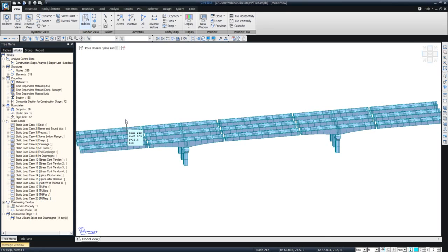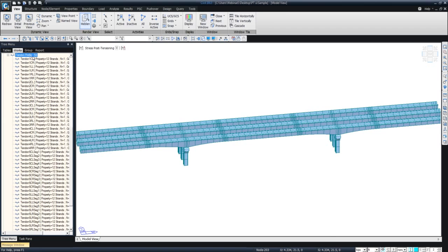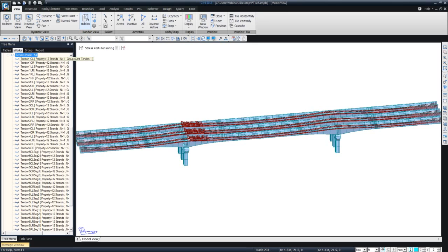Then we will pour the lid on top of it. So sorry, in this stage we'll apply the splice form here. Then we'll apply the post tensioning. Since these are precast members, I would like to draw your attention towards the strands layout and definition. If I just right click and say display, you can see there are post tensioning strands in the section.